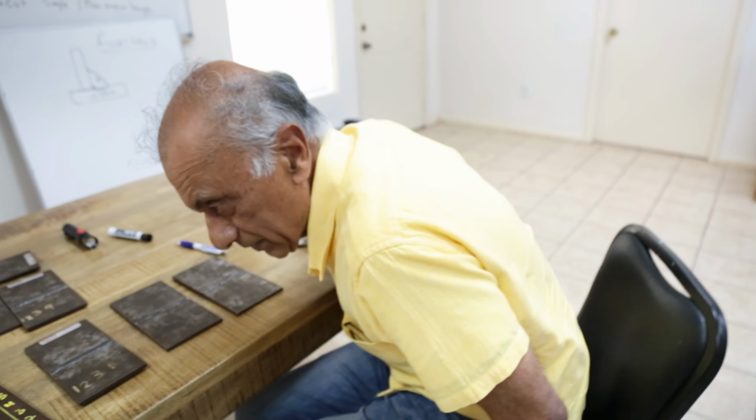And finally, I would like to say that in VT testing, taking photographs is very important. If you see, let's say, undercut, or you see porosity, you should take some photographs, examples, and include them in the visual testing report.